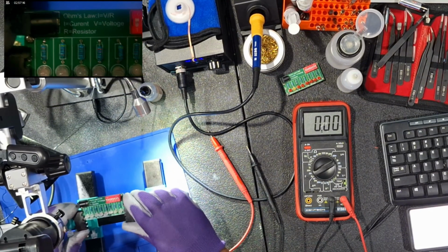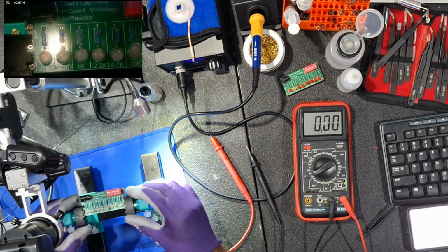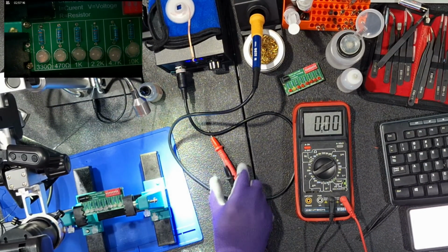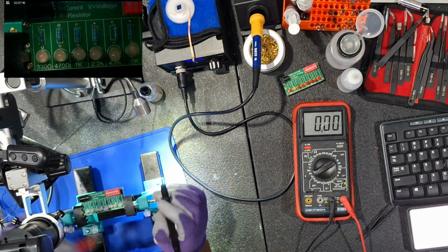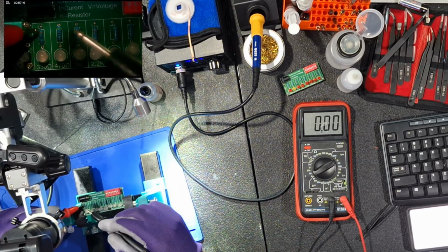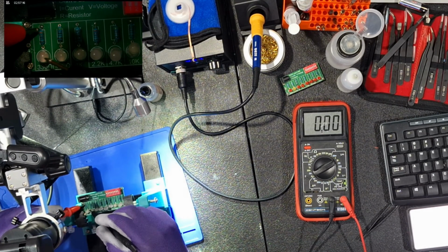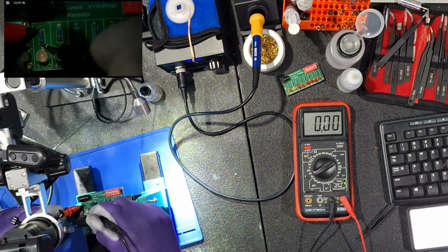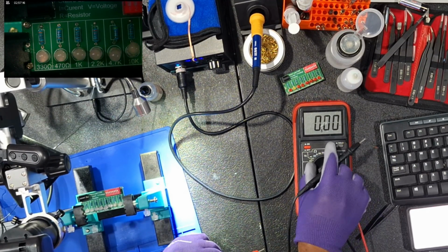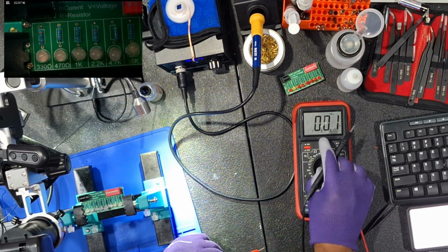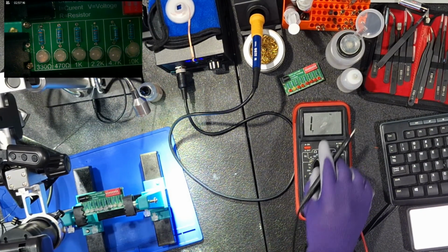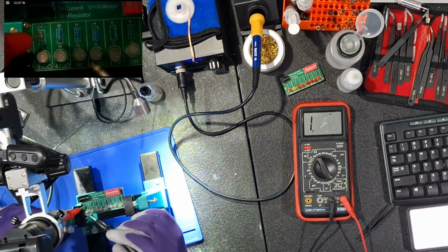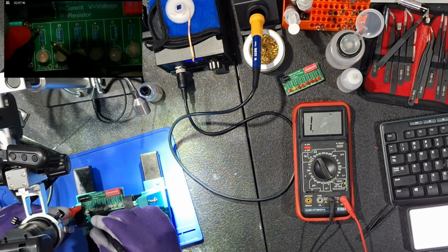This is how I do it with the multimeter, and this is the best way that's been working for me. Using the multimeter to find the value for the resistors, it's just a matter of putting the multimeter in diode mode. When you have it in diode mode, this is where you get the beep when you join both probes together. But one thing I found out is that in diode mode, it can't test for resistors higher than 1 kilo ohm or 1000 ohms.